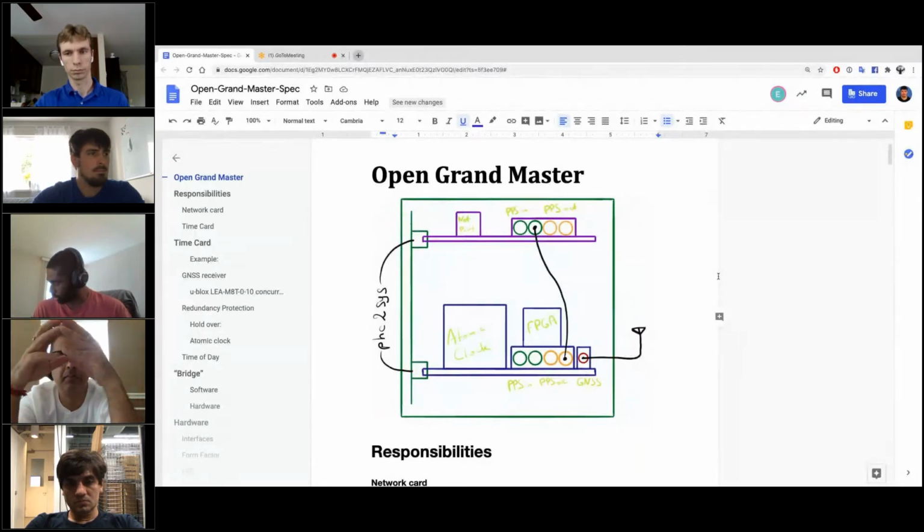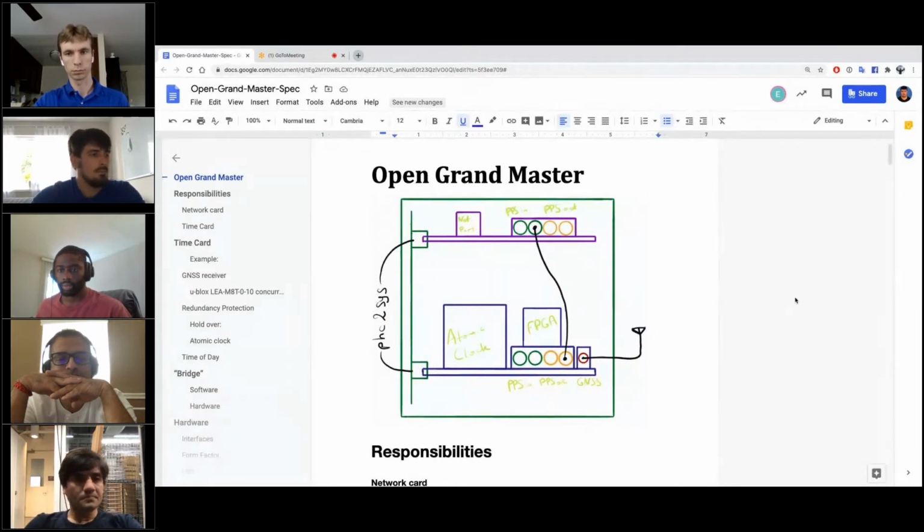Okay, software can save that. And then software can get another PPS in: you got a PPS in at 8 o'clock and 1 second and 300 nanoseconds. And later on, software can decide if it wants to readjust the clock by 300 nanoseconds, to adjust the frequency, or to ignore some of the samples because they are outliers. This is a completely algorithmic part.